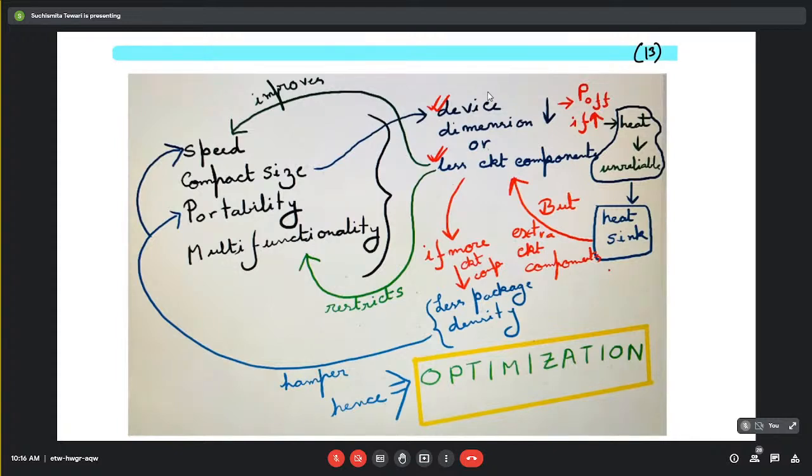And since at the off state some current is there in the output, there will definitely be some power loss, I squared R, simple. That power may be dissipated in the form of heat. So if the leakage power is increased when we scale down the device and it produces heat, it might affect the circuit performance of the entire system.